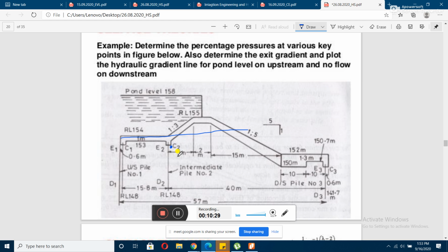So here there has to be a particular value. If the slope is going towards the upper side, it is going up, then there will be a reduction, or you can say a negative correction for slope. And in case of a slope like this that is going down, here you can understand the area is being reduced, so you can see the area is being reduced. So here there will be a positive correction, this E3 value will have a positive correction.